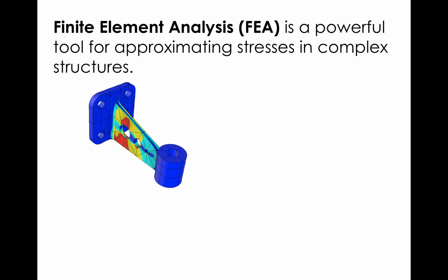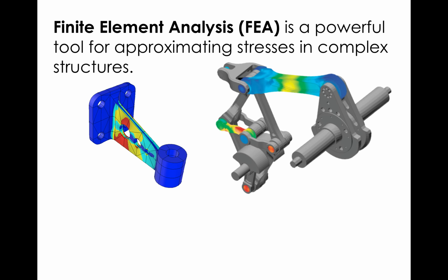Let's say this is a bracket, and that bracket is supporting a lot of weight at its end. Okay, so it's fixed on the wall, and you're going to load it way out here. You would look at maybe the stress profile because you're worried about it breaking across that center hole, right? So that would be an analysis that you might run if you were concerned about that bracket breaking.